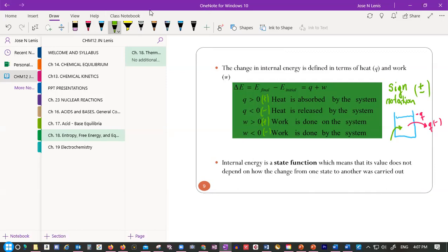Now it's from surroundings into the system. So you say, okay, the heat is positive. So you must learn first what is the direction of the process, and then based on that, you give the sign, positive or negative. Or if during the mathematical procedure you find that Q is positive, so you know the flow of heat goes from surroundings into the system, for example.